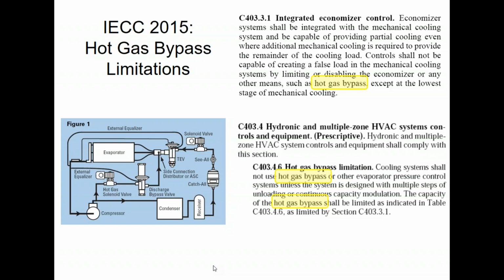So we already saw that once we're above 6 tons, we have to have multiple stages of compression, right? So really, we're only talking about stuff that's 5 tons and under. If it's 5 tons and under, single stage unit, you cannot put hot gas bypass on there. It's only like a weird scenario, although usually systems that small don't have additional zoning, so it's a non-issue.